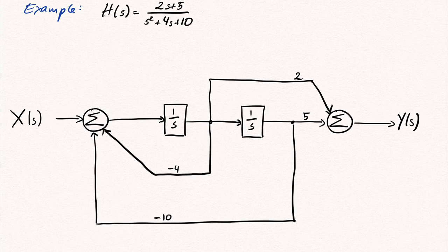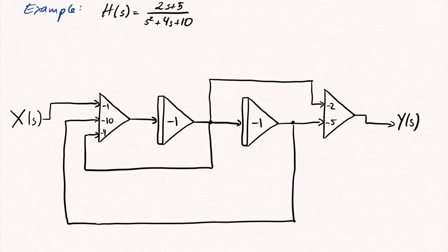Since we want to implement this filter using only inverting amplifier, summer, and integrator circuits, which all introduce negative signs, we have to keep track of how often the sign of a signal is inverted. For this, we change the symbols in our block diagram. The summers are substituted by triangles with the negative amplification factors, and the integrators are substituted by a triangle together with the small rectangle and amplification factor -1. To check if the output signal is calculated correctly and with the correct sign, we will mark all signals with a positive sign in green and all signals with an inverted sign in red.